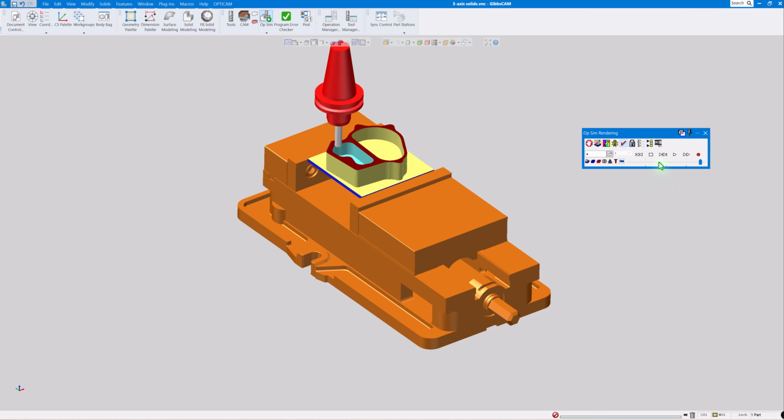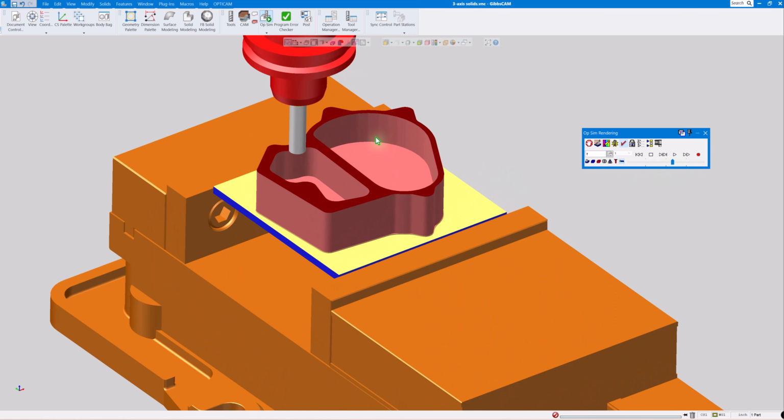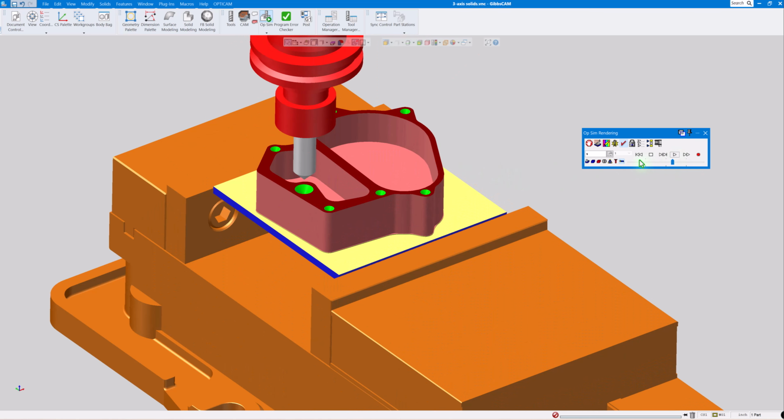Okay, that is done. Okay, now we want to finish the outside and finish the inside there. That's with the same tool, 3/8. And the same thing with the cavity over there. Finish the floor, finish the sides. Now we change tools. We need to go to chamfer now. Actually, we're going to drill the holes.